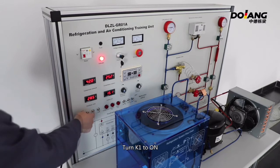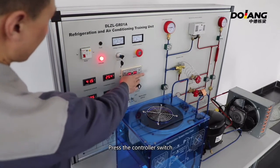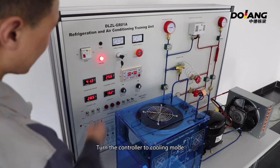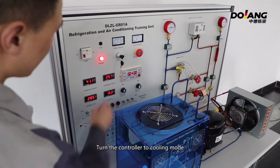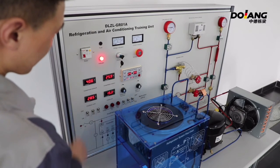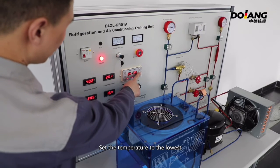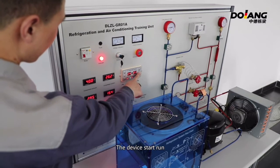Turn K1 to on. Press the controller switch. Turn the controller to cooling mode. Set the temperature to the lowest. The device starts to run.